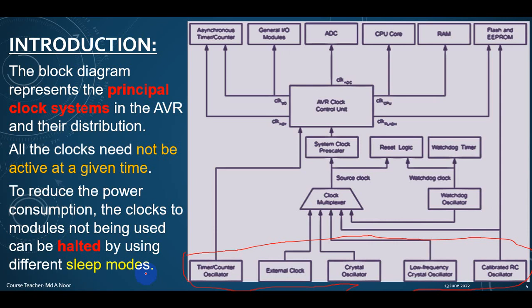Okay, so to design a power saving, that is, power friendly application, you need to use the sleep mode properly. Today's class will introduce you to the sleep modes, and when you write the program, keep in mind that when you go for actual production, make sure you properly utilize the sleep mode for reduced power consumption, so that people don't need to change their battery every day.